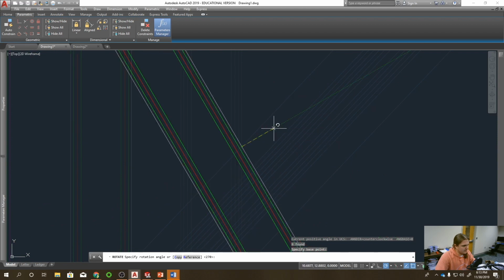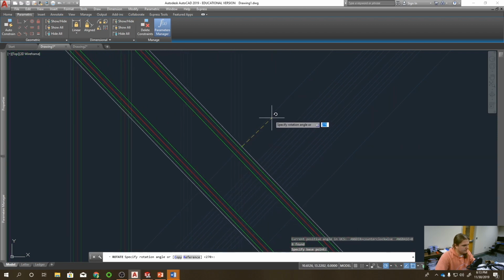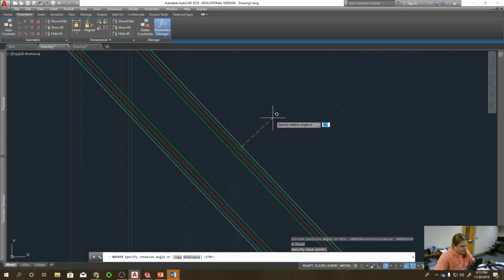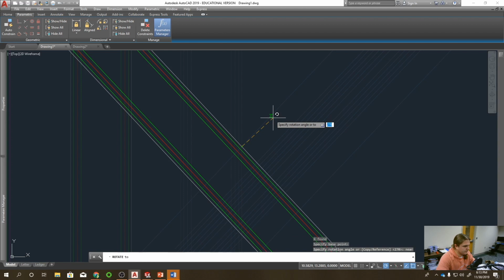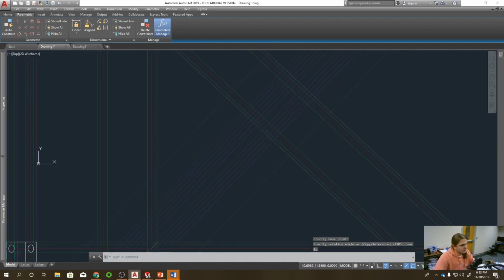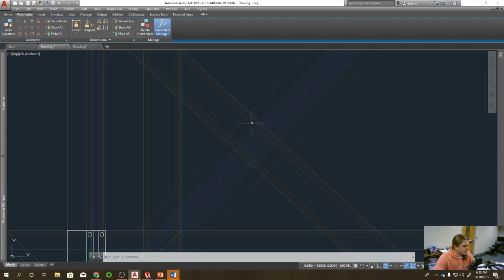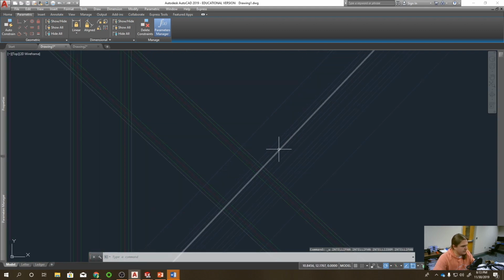As you can see, there's nothing really snapping to it. Actually, can I go? I'm going to try one thing here real quick, and then I'll show you the other way I would do it. Okay, so now I just did a near constraint there, typing NEAR, and that seemed to work. The other way to do it